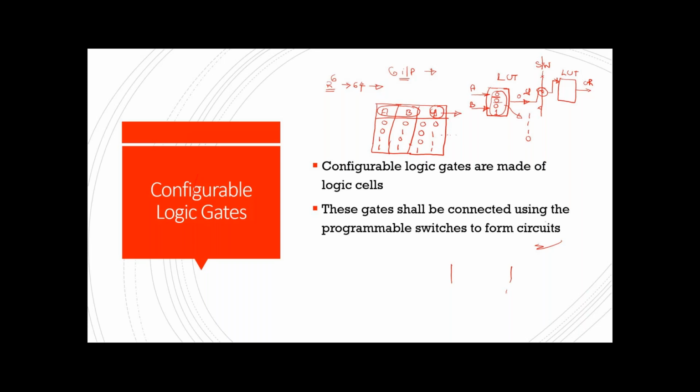There are some questions like, FPGA is highly costly compared to an IC we design using physical design, so why do we still use it? That is a catch actually. Whenever I say ASIC flow design, that chip will become cheaper only if you are producing in mass production, maybe a 1 lakh or 2 lakh quantity. If it is mass production, then only it's going to be very cheap.